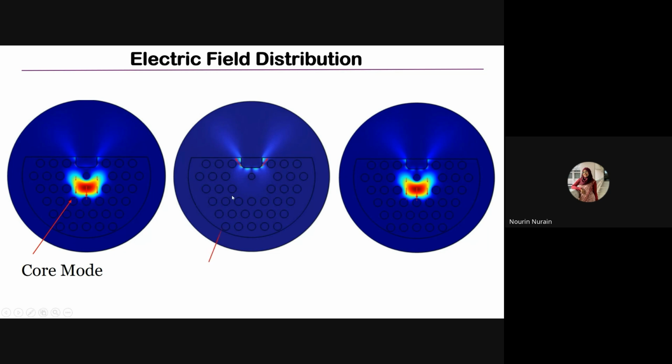And in the second picture here, light escapes from the core towards the metal dielectric surface, and here the surface plasmons couple with the photons, and as a result light gets trapped in this D-shaped microchannel. This is what we call the surface plasmon polariton mode. And lastly, this is called the surface plasmon resonance mode. Here basically the phase matching condition occurs when the surface plasmon polariton mode and the core mode occur at the same time. We get the surface plasmon resonance mode.